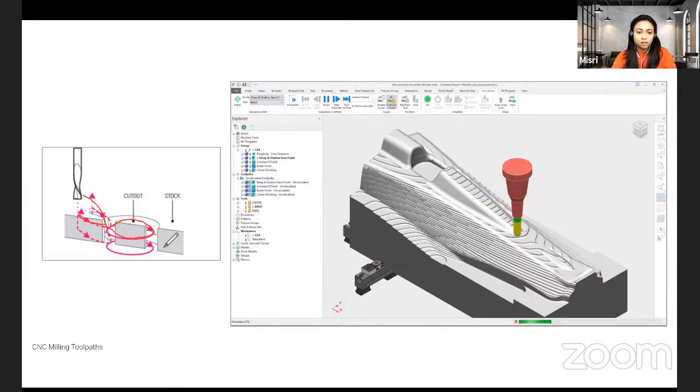If you were to see the distance, there's a rule of thumb based on the diameter of the drill bit, say for instance this was 0.5 in diameter. If it's a small object, like you see right here, and soft, like foam, it would probably be okay to go deep in the first pass.